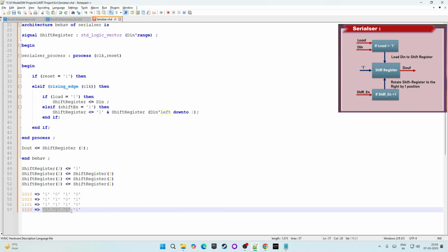But if you force 0 value here, then after the whole transmission is complete or all the bits are transmitted, because of this 0 value, our transmission module will read this as getting a next data, and that is not correct, right? So we have used this value 1 instead of value 0 here because our default state is 1. Now if you are working on some different protocol that has value 0 as the default state, then you will insert 0 here.